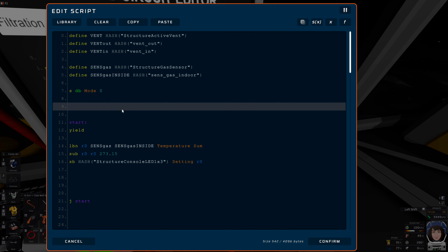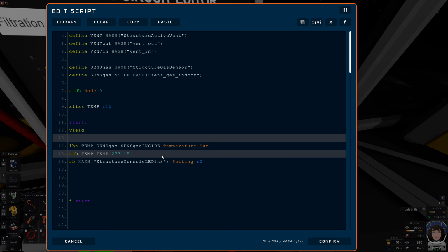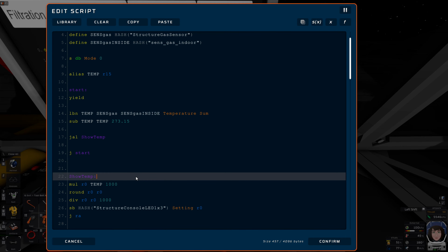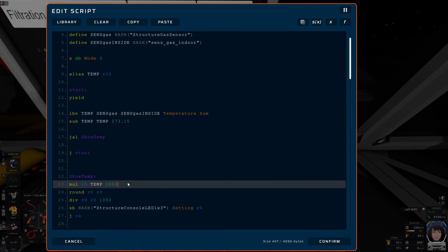Let's take a little detour. You don't know the very important alias statement yet. With this I can say I give a register a name, and henceforth I can address it by still the register of course, but also I can use this name. Why would I do this? Because sometimes a value is one that you want to keep around for the entire main loop. Not just a temporary value like I did here in this situation, but I want to keep the temperature around. So with this kind of global value, it is easy for me to just digest it down here in a subroutine.